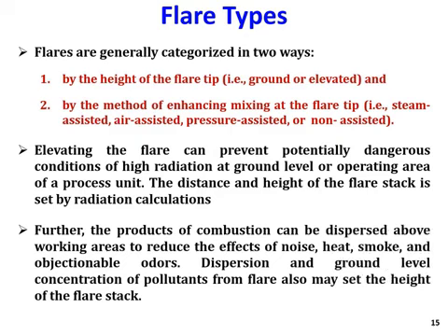Then okay, flare type. The flare systems, I'm now talking about this part, is important. Flare systems are categorized in two ways. So height of the tip of the flare. Tip of the flare is the toppest part of the flare. So the height, how far it is from the ground, if it's like close to the ground or it's elevated. So that's one of the categories. One of the way that we categorize the flare.